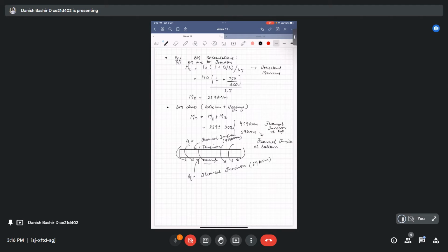So we will calculate our dimensionless quantities, the parameters that you studied in the flexural design of the beam. So, design of top steel. We will calculate the factor R1. R1 is actually M equivalent 1, ME1, divided by BD square. So we will take this as ME1, M equivalent 1. We will take this as M equivalent 2.